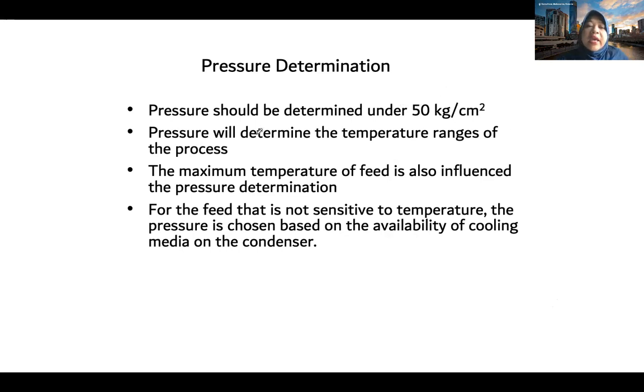If you remember the PXY diagram, at higher pressure you have a narrower separation, so it's better to have as low a pressure as possible. For a feed that is not sensitive to temperature, the pressure is chosen based on the availability of cooling media on the condenser.